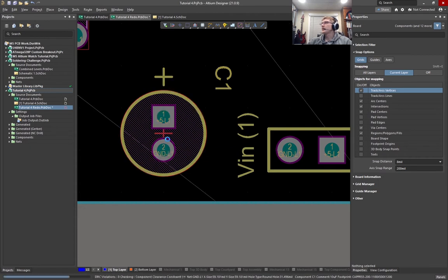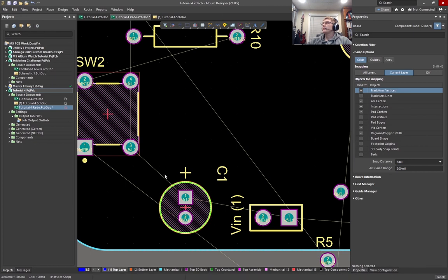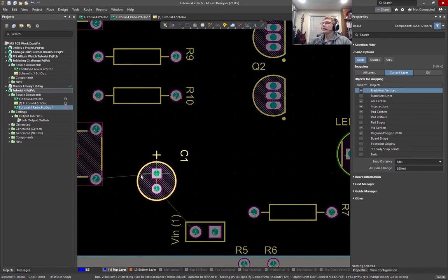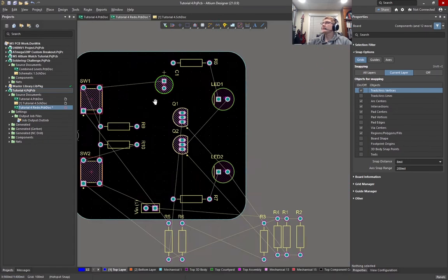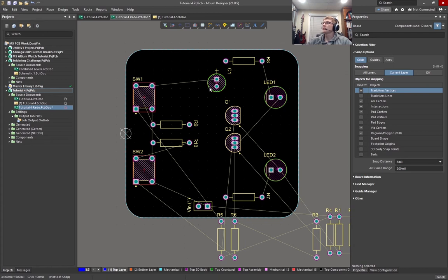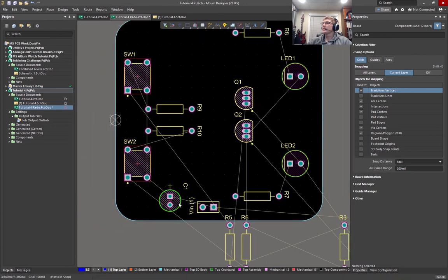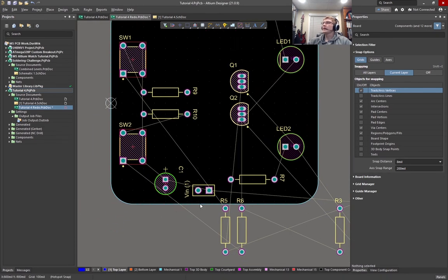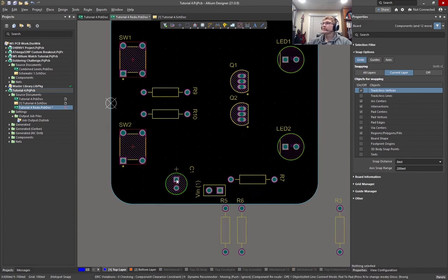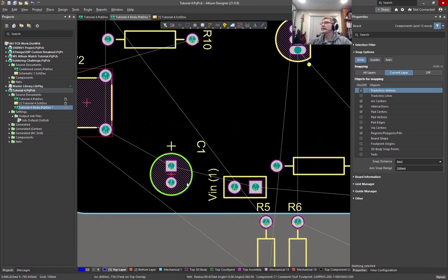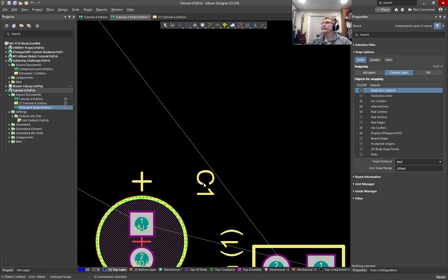This is a capacitor, and so here's a good example of something you've got to be careful about. There's a lot of 5-volt things, because a lot of things connect to power on this board. So it's going to look like it makes sense to put it somewhere over here. And the truth is that it doesn't, because this capacitor is just there to filter the input power. So I want to make sure that this is actually close to the input. And there's going to be a couple cases, things like pull-down resistors and stuff like that. If it's a pull-up resistor, you want to put it close to the pin that it's supposed to be pulling up. Filter capacitors, just like I'm doing here. These are just things to think about.